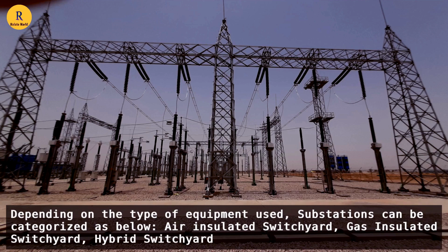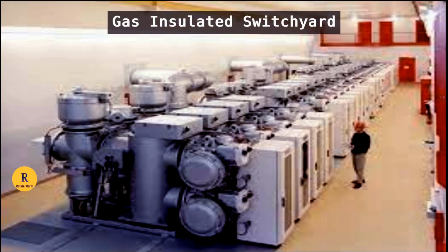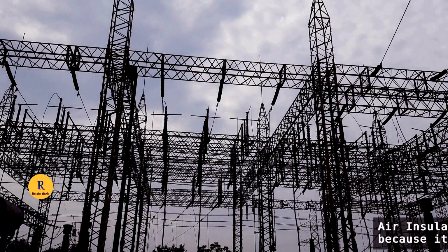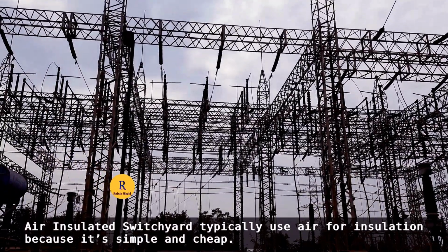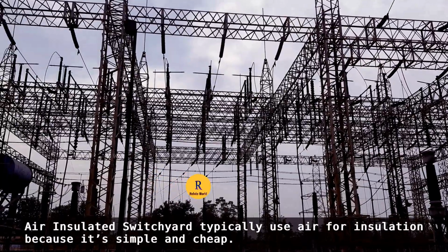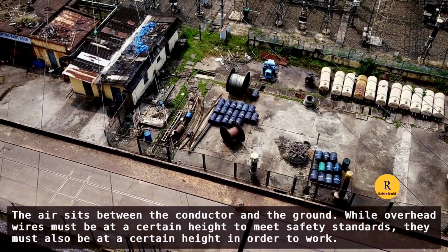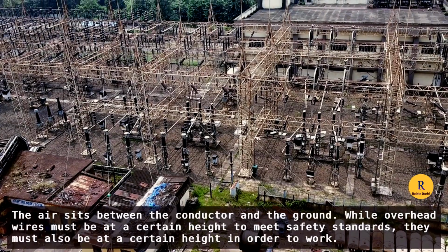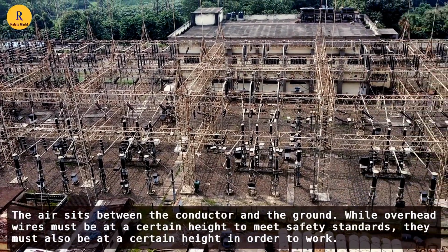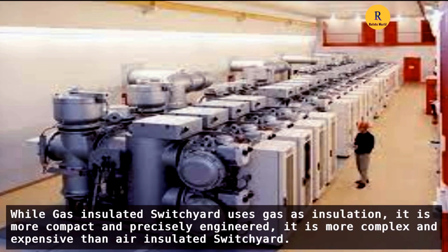Depending on the type of equipment used, substations can be categorized as: air-insulated switchyard, gas-insulated switchyard, and hybrid switchyard. Air-insulated switchyards typically use air for insulation because it is simple and cheap. The air sits between the conductor and the ground, while overhead wires must be at a certain height to meet safety standards.